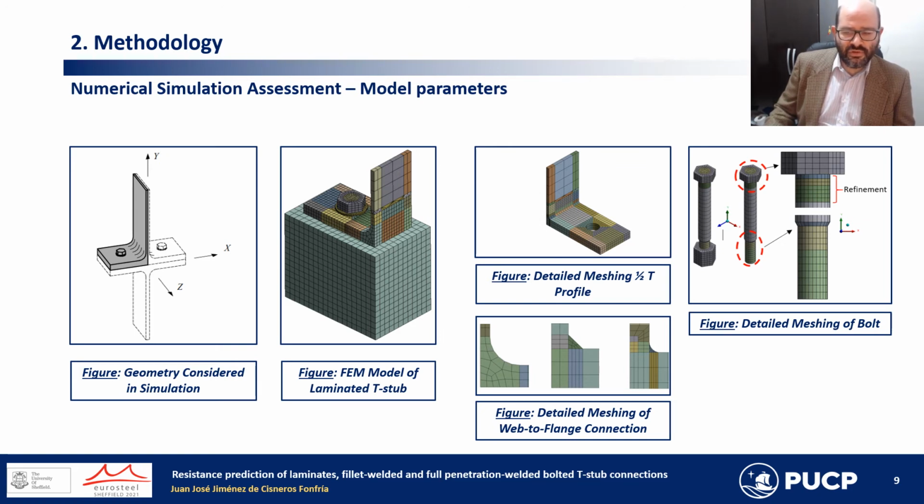The base was also modeled, and joint elements were considered to simulate the interaction between parts when the tension load is gradually applied from zero to the end of the simulation. Proper boundary conditions were considered to define the symmetry of the model. The model was calibrated with experimental tests performed by comparison of the force displacement curves and also checking mesh convergence.